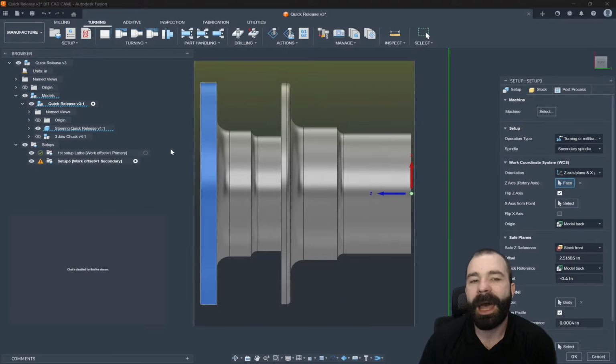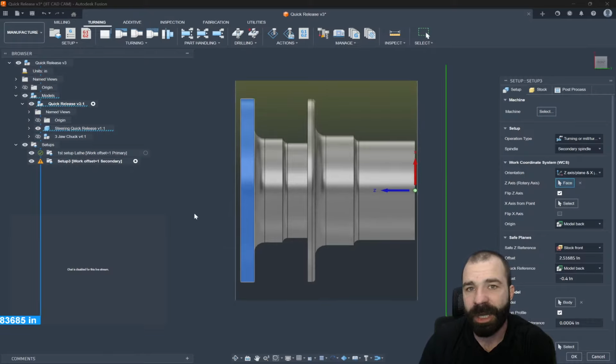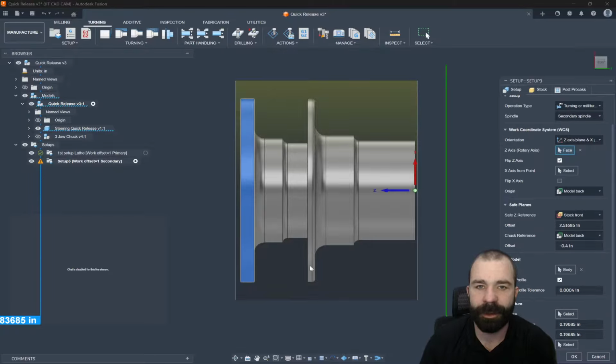To me, I don't pay too much close attention to the G code at the machine. I pay attention to distance to go. And if I did have to bore those jaws out, I can simply reference off the deepest part of my jaws as my stop. So again, we're going to go ahead and scroll down here a little bit further.